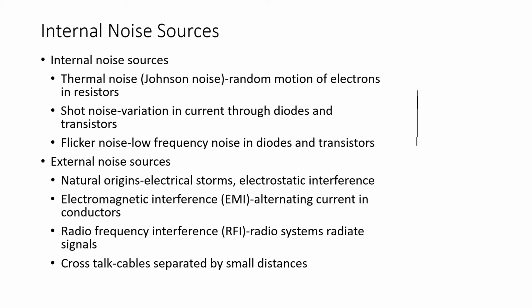Sometimes they refer to this as 1 over F noise, in that if we look at the noise voltage as a function of frequency, we would find that graphically this response looks something like this. So the noise is predominant down here in the lower frequencies. The noise is, of course, less, as you can see graphically, at high frequencies. Again, nobody understands exactly what the source of flicker noise is. They just know it's there.